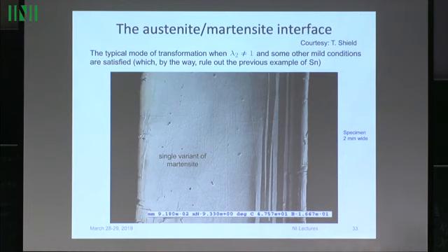Yeah, that's all. And could you do this also with magnetism? Would you expect the same? Oh, can I field induce the phase transformation? So if I kept the temperature the same, can I apply a field and get the austenite? Not in this material, because it would be very hard, maybe with very strong fields, but in other materials it'll be quite easy. And that's the basis of the energy conversion in ferromagnetism that I'll discuss. The effect of field on transition temperature will be an important part of that. But not in this particular material.